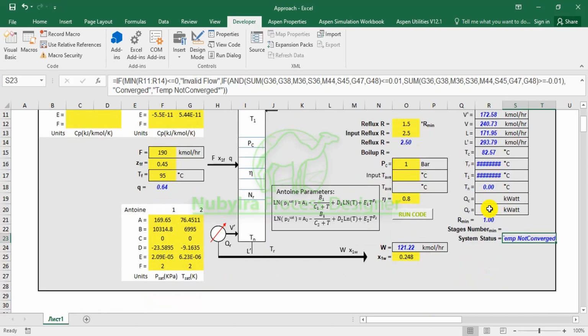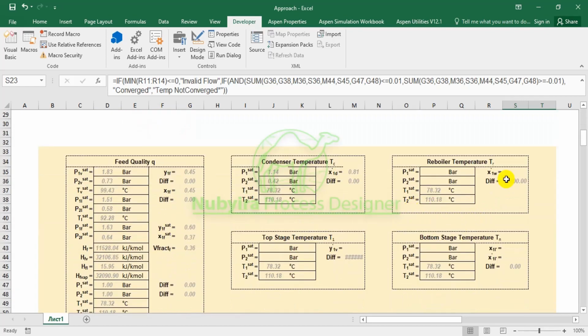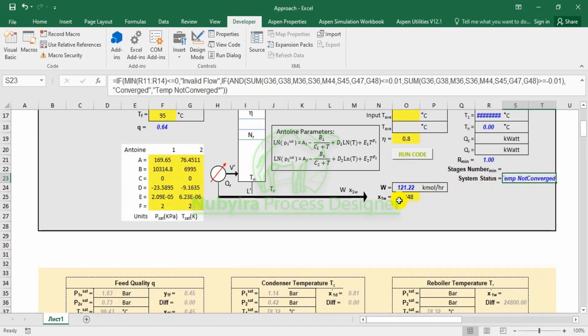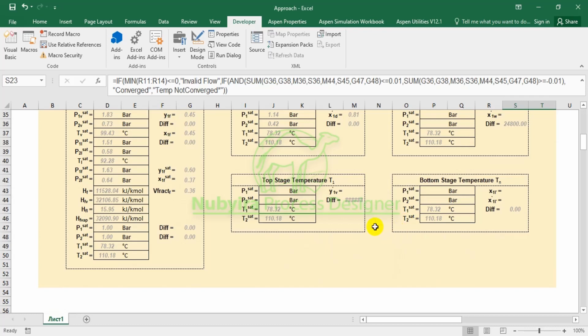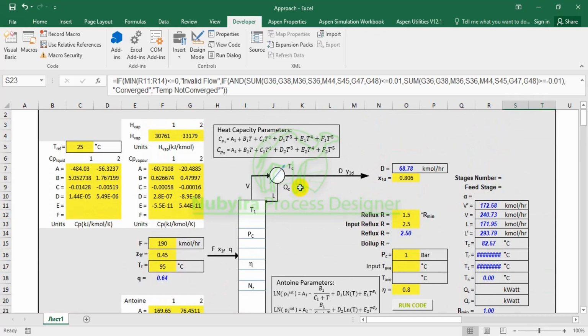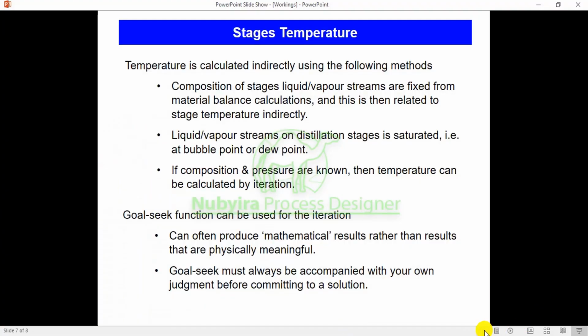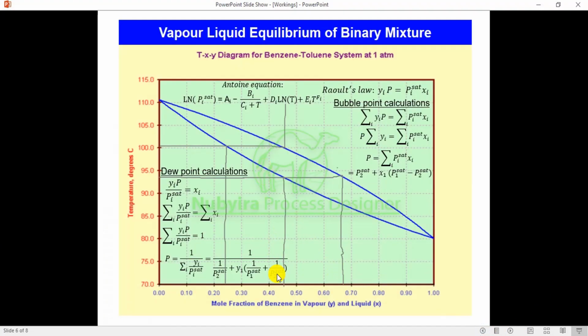So I'm going to do the reboiler, and the assumption for the reboiler is this mole fraction, you understand? And for the first top stage, because you have a total condenser, there is no partial saturation. So it's just like having these two sections over here. What is coming here, the mole fraction is the same as the mole fraction that is coming in. We are pulling from the condenser, coming down from here, so the mole fraction does not change.